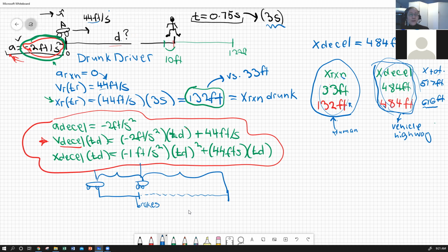We're going to basically say, okay, the speed limit's going down because we're going to assume this reaction time of 3 seconds, and we know what distance you can see ahead of you on this roadway, because maybe it's hilly, whatever. You're coming out of the hill, your line of sight is going to go into the hill.